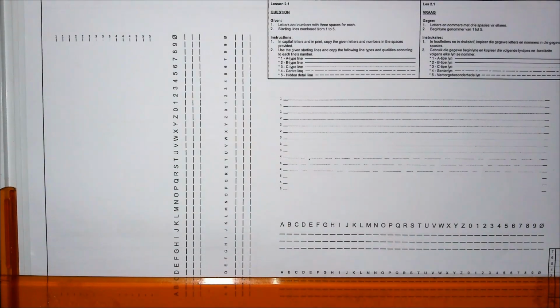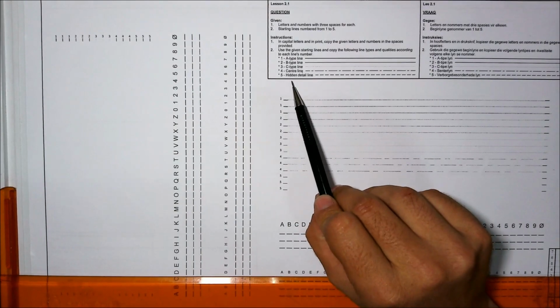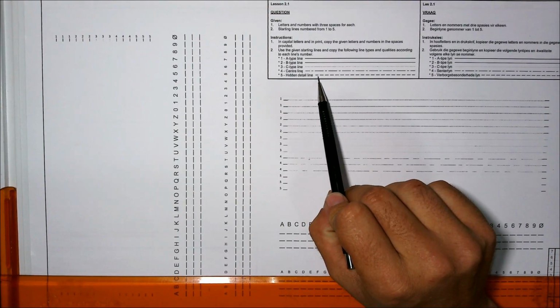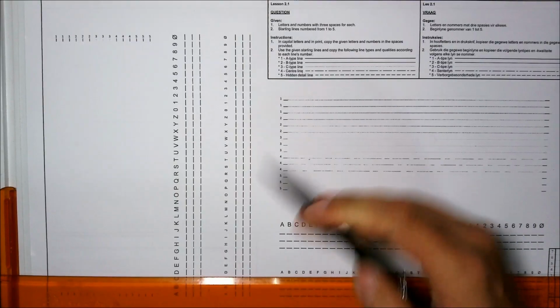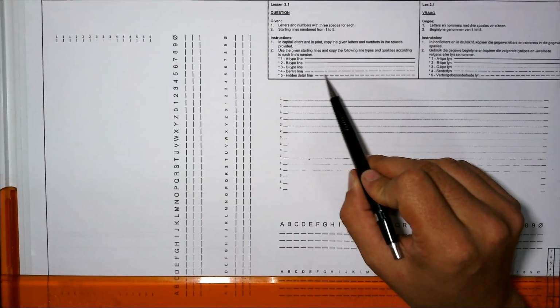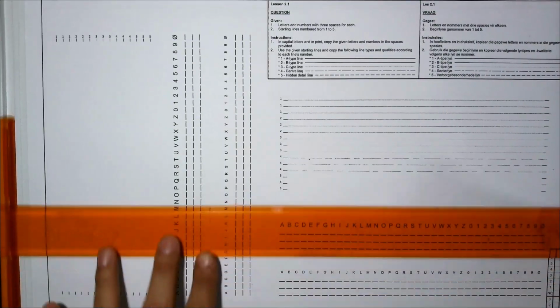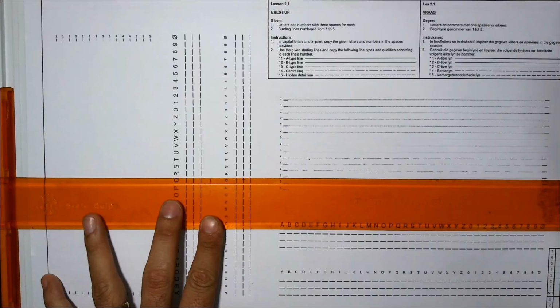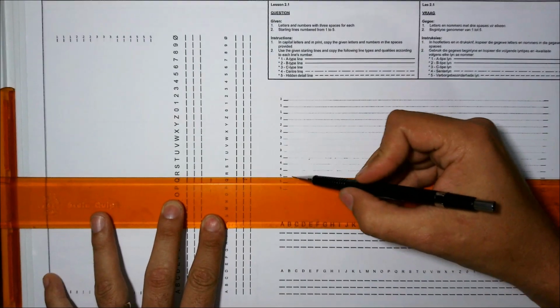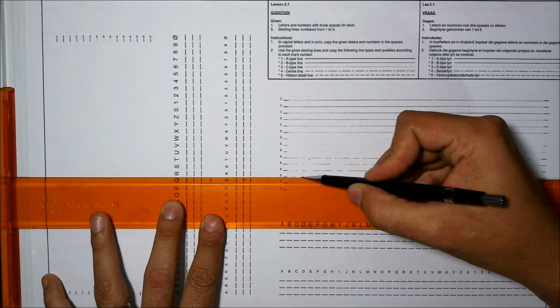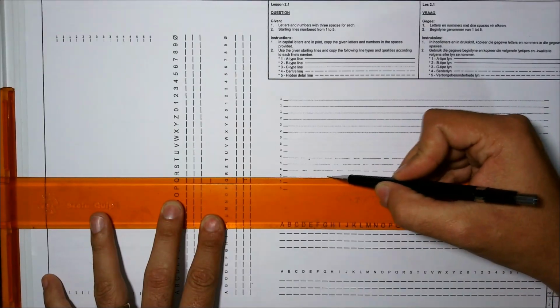All right, so we are finished with the center lines. Now, having a look at number five, that's the hidden detail lines. That means you are looking at something that's behind an object and you indicate it using these dash lines. This is also going to be a B quality. So, number five, same story. You take this quite slow, B quality, and this is now where you have a dash line.